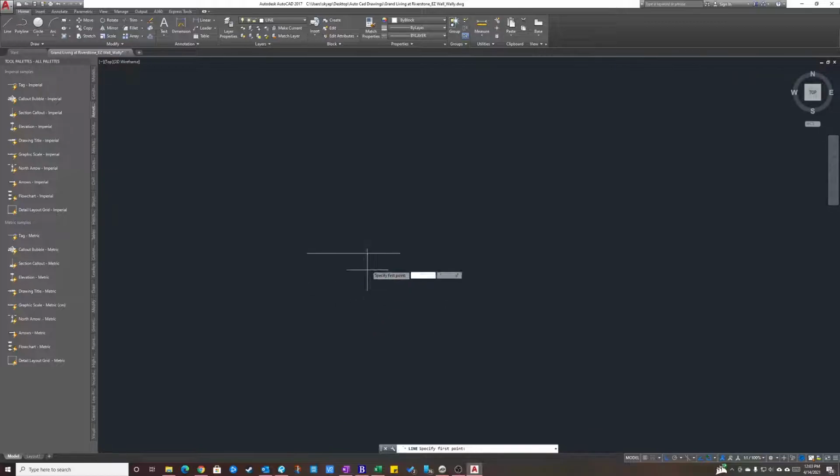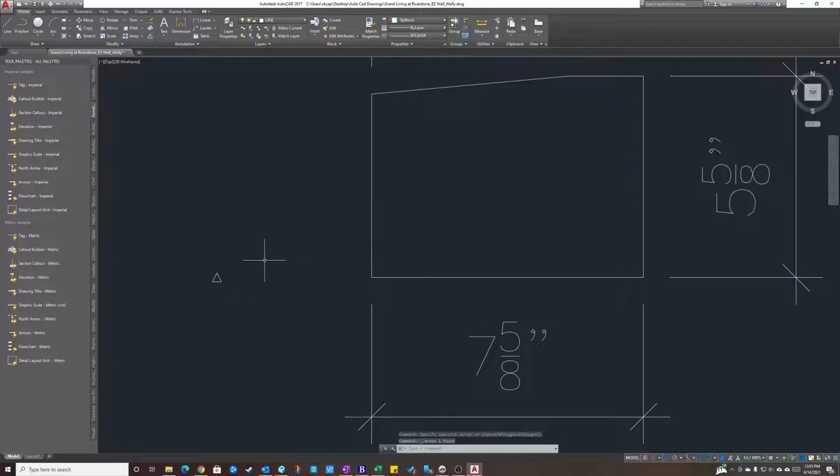We're gonna zoom in, click in the middle, and make that 1/4 of an inch as well. That's 0.25. And enter. And then we're going to repeat that line. We start off onto the side, click in the center, click off onto the side, escape. Then we select our middle line and delete it. All right, now we have a triangle.